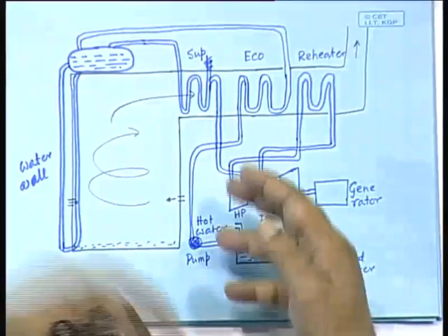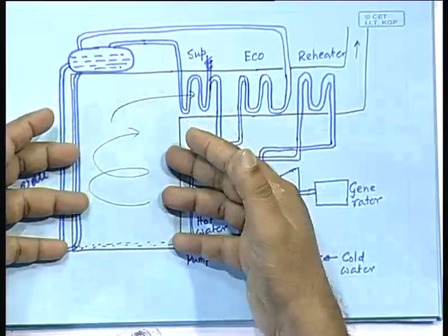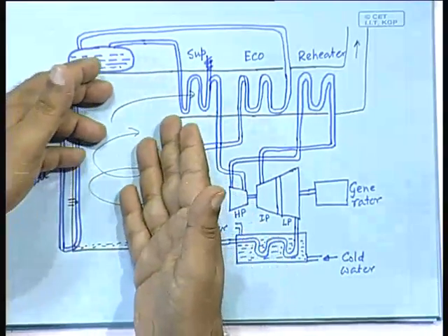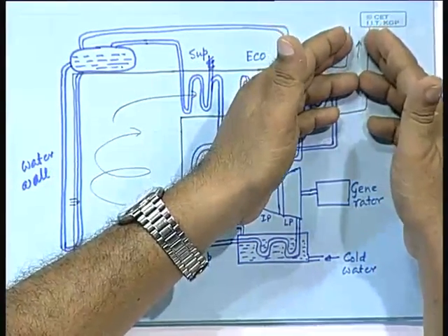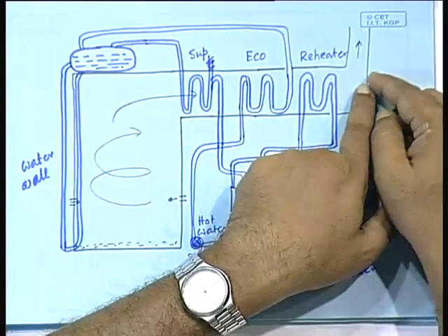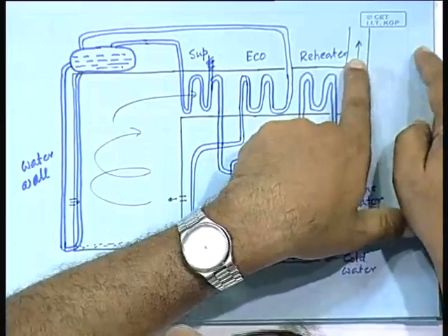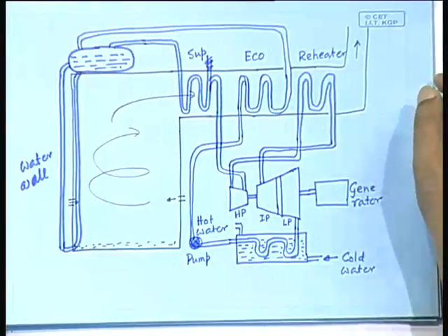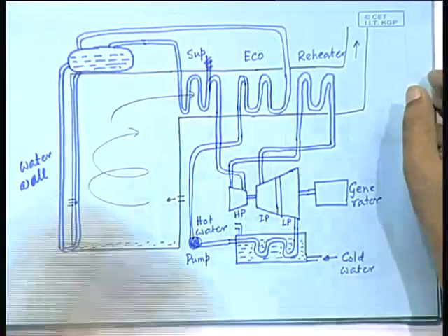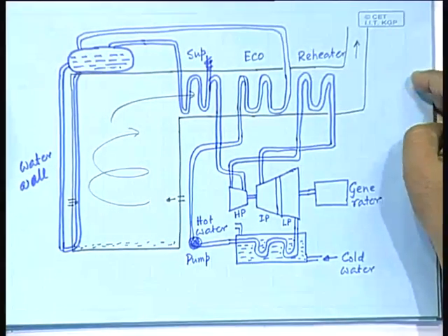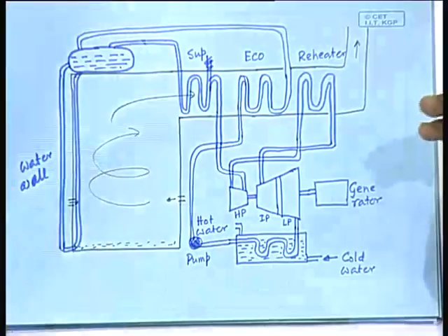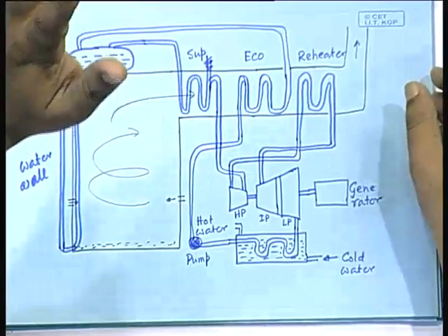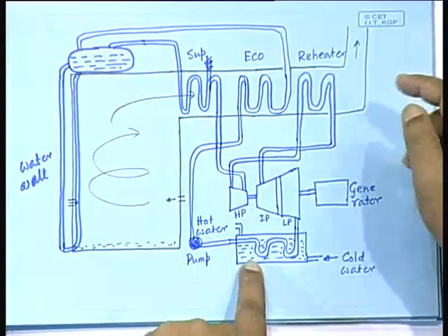So, here there is a heat generation, and part of that heat is taken out fruitfully, but part of it is still there, right. Can you bring the temperature of the flue gas here down to room temperature, so that no heat is really left out? Is it possible? Let us address this question. That would obviously be one way of improving the efficiency. I do not allow any heat to go out. Okay. One source of inefficiency is here.